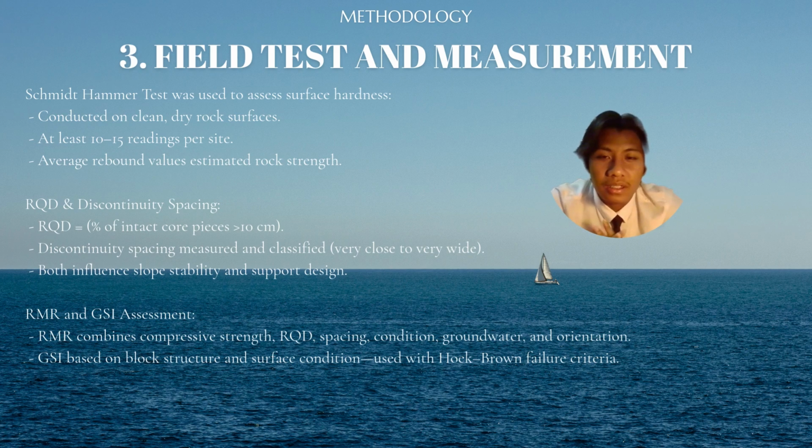Alright, so number three is the field test and measurement. So first one is Schmidt hammer test. We conduct it on a clean dry rock surface and we take at least 10 to 15 readings per site. And next is RQD and discontinuity spacing. And lastly is RMR and JSI assessment.